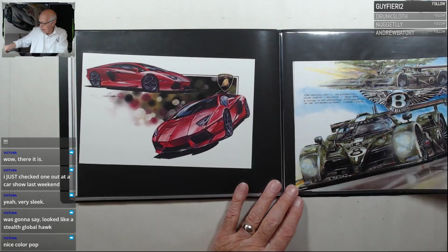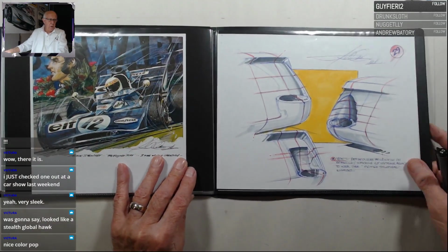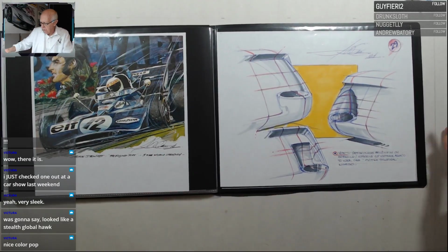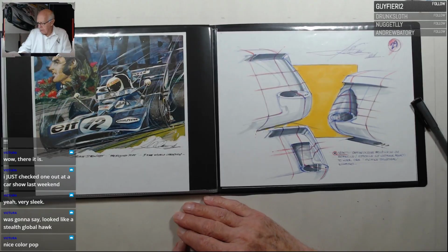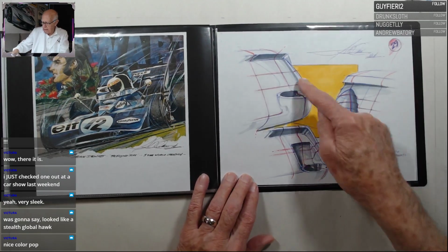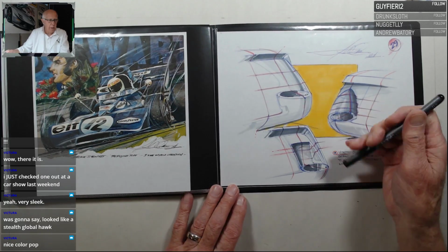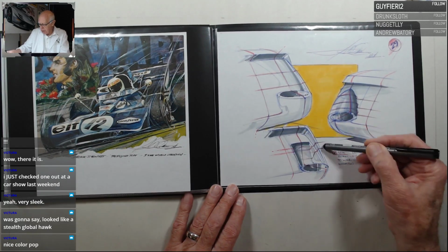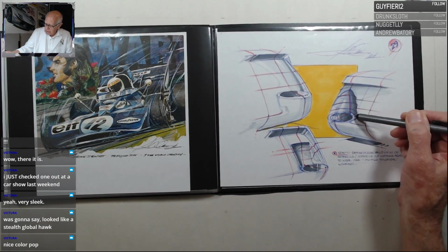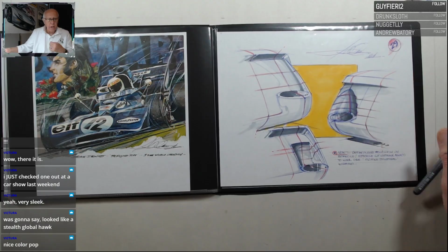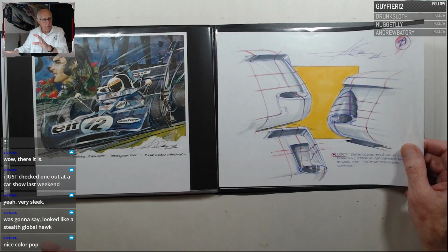Last but not least, we've seen that Bentley piece again here, seen that Stewart piece. This is a little study in contour and section work that was done for Honda, for a motorsports piece, off-road vehicle. We did this a little bit for them, just to show them what the surfaces look like. And again with circles, how they begin to look at that cup holder container, variation 1, with another variation here, how it channels itself back out into the actual injection molded part. And again, it serves a little conical piece that comes back and changes section, and how those circles influence what the dies are going to look like, and how to begin to look at that from an engineering perspective to manufacture the part.